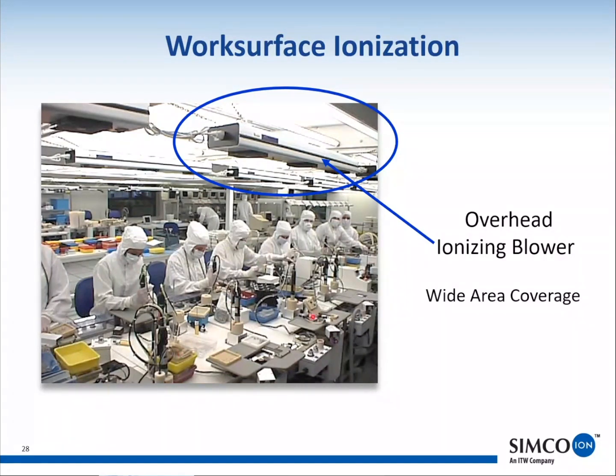There's a whole engineering process to understanding how close you can put the ionizer and how far away it can be, versus fan speeds, versus how fast things are operating. If you've got a very slow operation, the items are sitting there longer underneath the ionized airstream, so you can tolerate a longer decay time. Versus, you can imagine a pick and place machine where parts are moving very, very fast. You may need a decay time that's much, much faster.